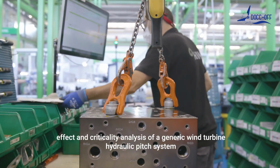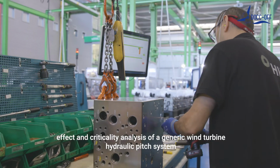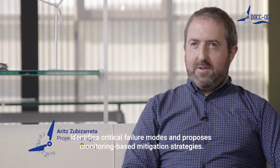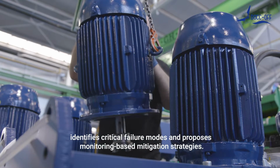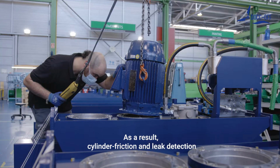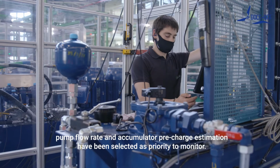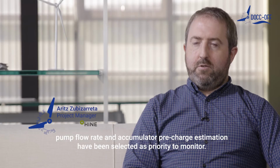The failure mode, effect and criticality analysis of a generic wind turbine hydraulic pitch system, carried out in the framework of Docc-Off, identifies critical failure modes and proposes monitoring-based mitigation strategies. As a result, cylinder friction and leak detection, pump flow rate and accumulator pre-charge estimation have been selected as priority to monitor.